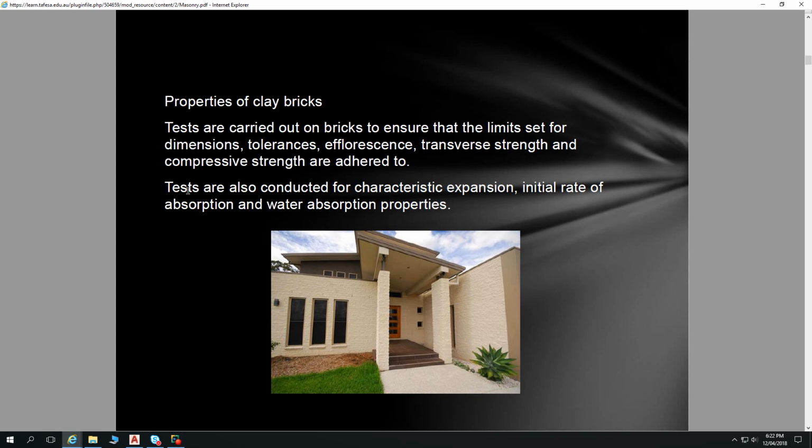Typically you see it on concrete, but you see it on bricks as well, to an extent. In its extreme form, it can be quite powdery and flake off. If you run your thumb along it, you'll get a whole lot of white powder on your fingers. Typically you see it on carport slabs, because weather comes in, soaks into the concrete and then dries out, and you get these lines of dissolved salts. Basically that's what it is, dissolved salts with a few other minerals in it. That's what efflorescence is.